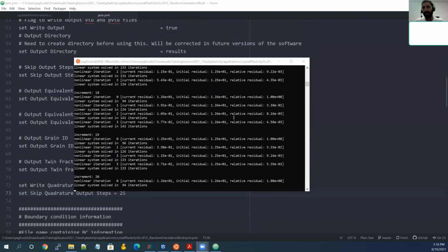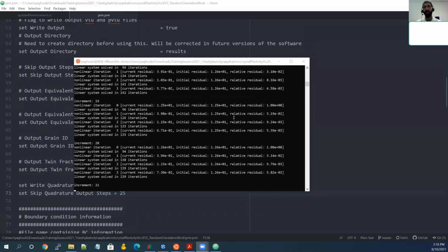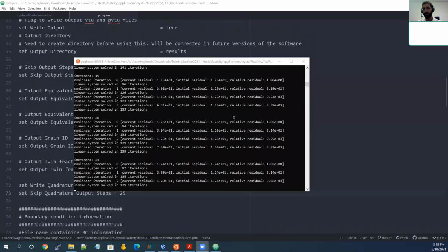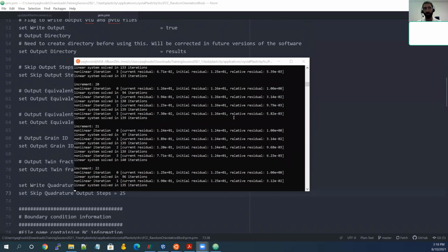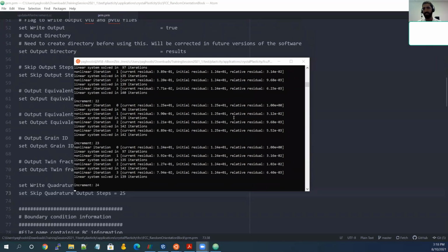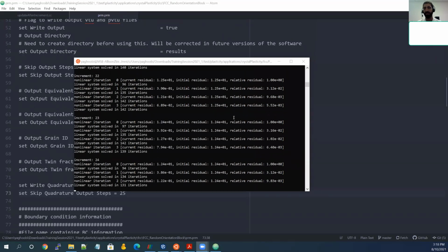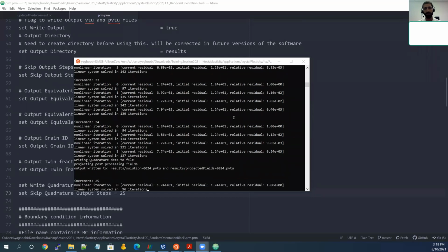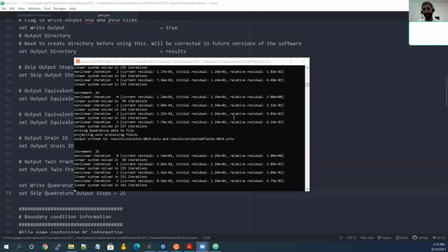There is some memory reasoning behind that. But in some applications like periodic boundary condition or element deletion application, you cannot use set refine factor. So that might be one of your limitations.